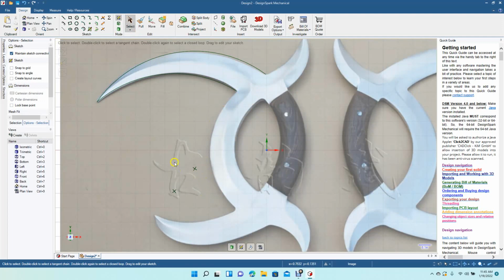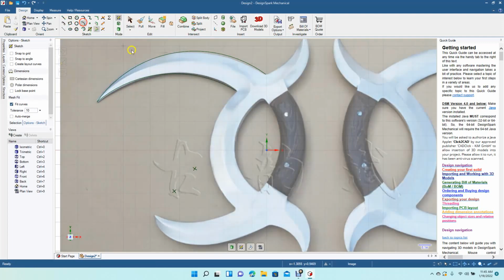Now we're going to go ahead and get that 3-point arc. We're going to go from here down to here. We'll just go straight. We're going to go 1.037 inches, and then we're going to bow this curve out to 97.2 degrees. It's going to be our angle.